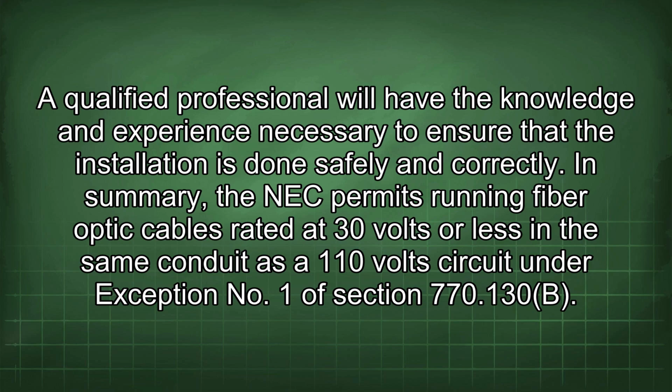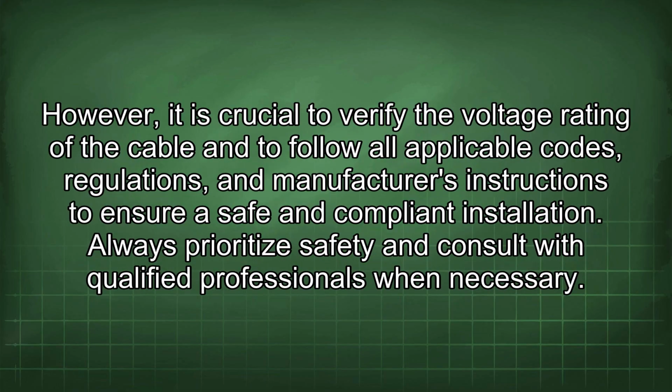In summary, the NEC permits running fiber optic cables rated at 30 volts or less in the same conduit as a 110 volt circuit under exception 1 of section 770.130(B). However, it is crucial to verify the voltage rating of the cable and to follow all applicable codes, regulations, and manufacturer's instructions to ensure a safe and compliant installation. Always prioritize safety and consult with qualified professionals when necessary.